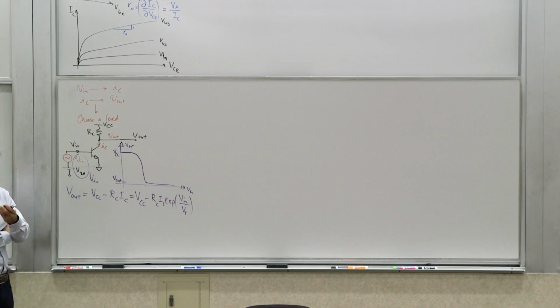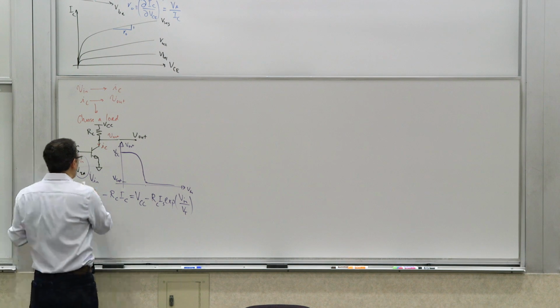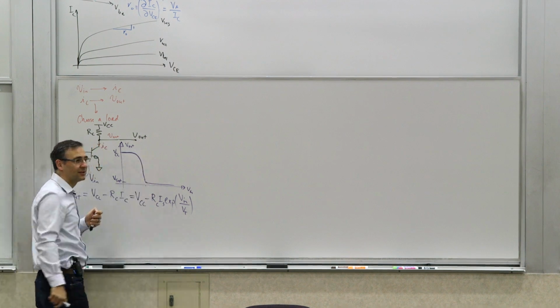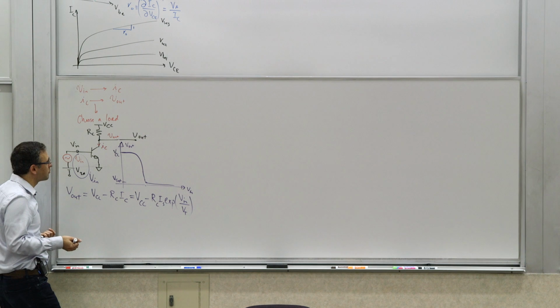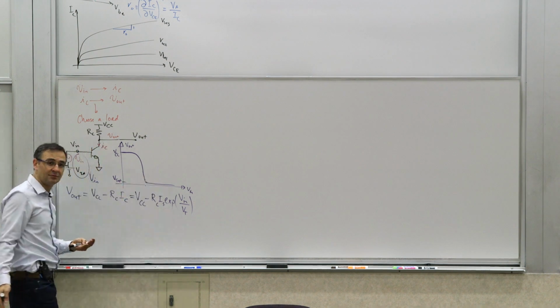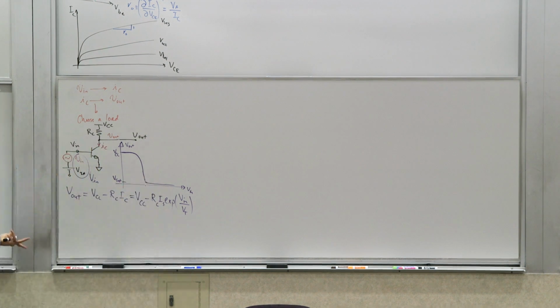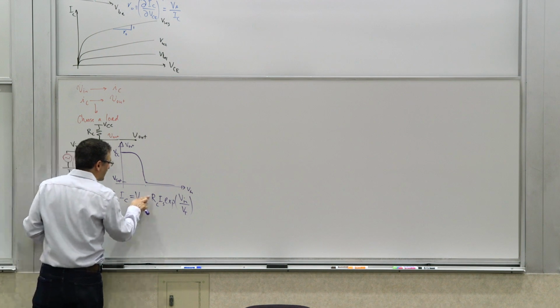One thing is that it's inverting. So that's one observation, right? Because when the input goes up, the output goes down. So it's an inverting gain stage. That's a good observation in that sense. So they go in opposite directions. So that's good. It's highly nonlinear. And we'll see why that matters later on.